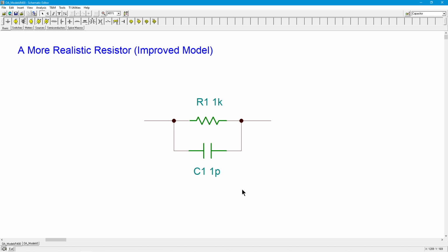You could make a super, super accurate model of, let's say, your op-amp, but the question then becomes, well, how complicated is it? The more complicated it is, in other words, the more components it has to make it more accurate, right? There's two components here instead of the original one resistor. The more components you add to make it more accurate, the bigger the computational hit.